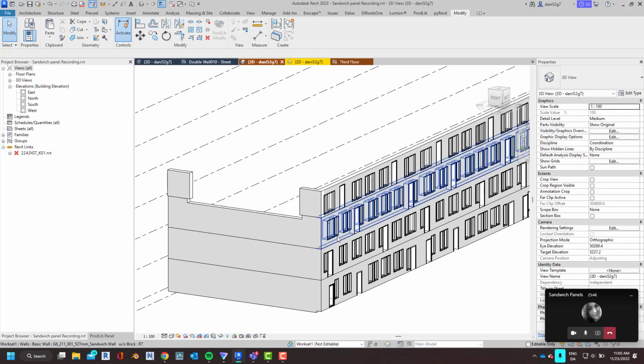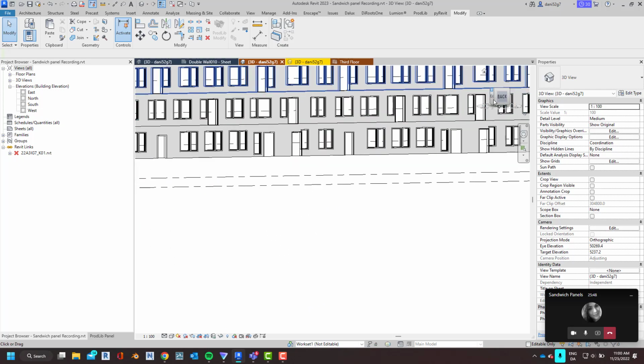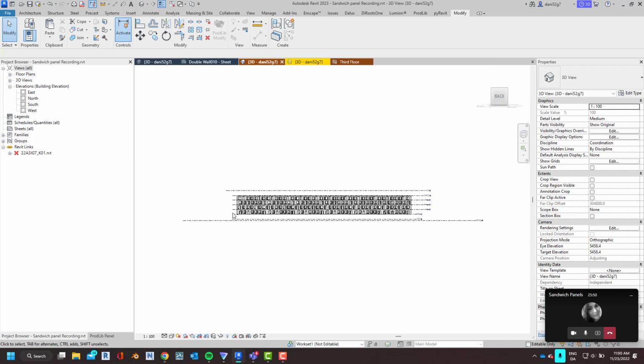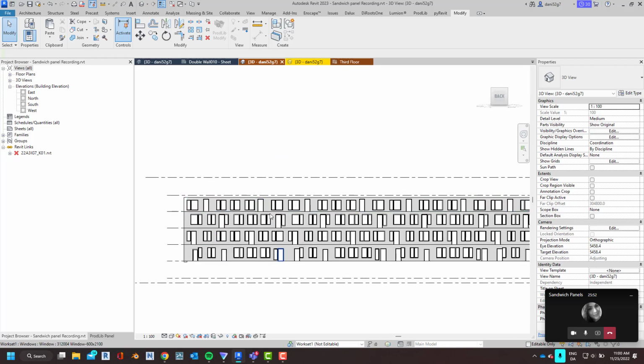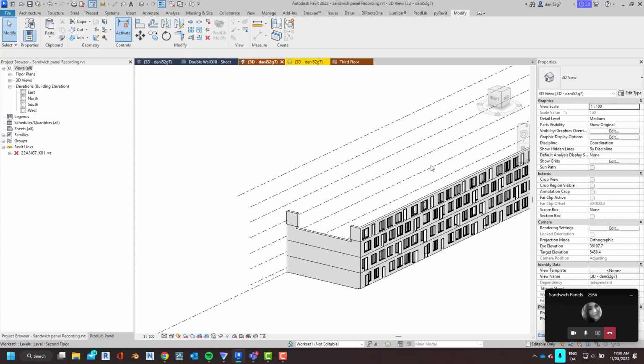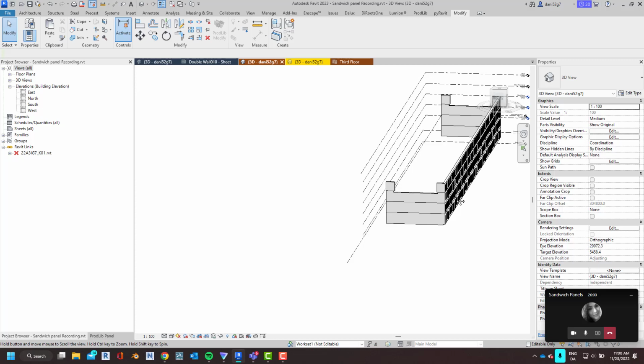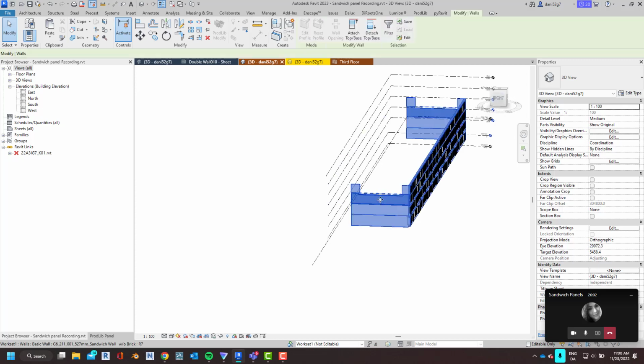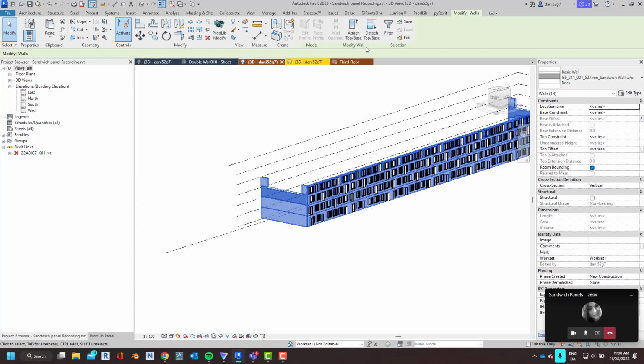In this method I'm going to do it manually, since we want to have control over where the splits occur. So we're not even going to load in the precast tools yet into this model. We're going to select all the walls, and we're simply going to create parts.